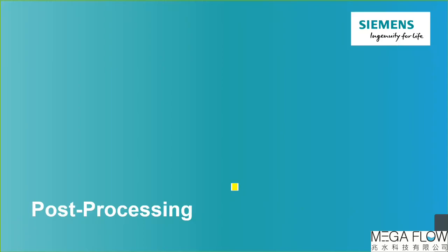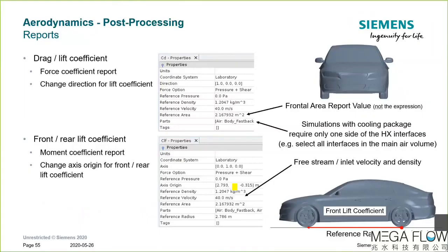Post-processing, that's a quick one. I'm not going into the details here because drag and lift coefficient setup should be really straightforward. One comment I would like to make here is the frontal area. Please do not use the frontal area report expression.